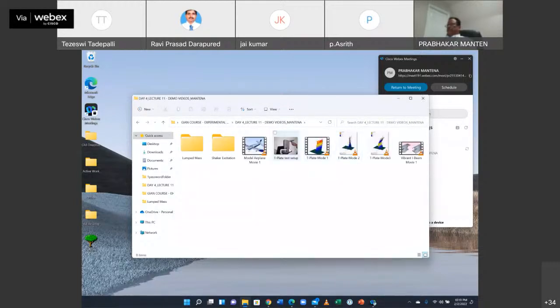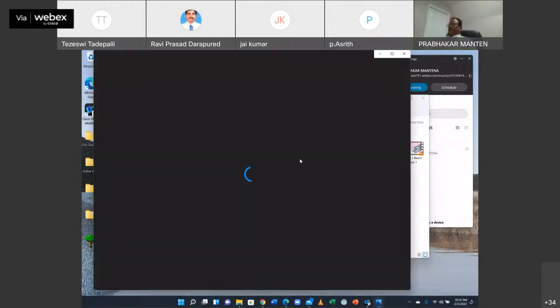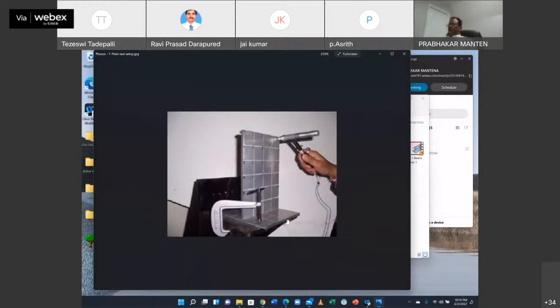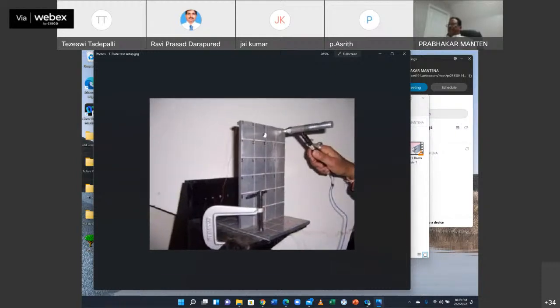Okay, this is the whole modal analysis we do. We have a standard fixture with a T-plate attached. You can do the whole modal analysis on the whole thing, including this, but mostly students focus on using the cantilever portion of the plate. They put an accelerometer somewhere in the region over there, then start doing a complete modal pattern with a hammer, getting each one of these points. They discretize, and this discretized data is fed into the software. I think the modal analysis software here we changed over the years. The older one is gone. More recently we got a very good one. I don't remember the name.